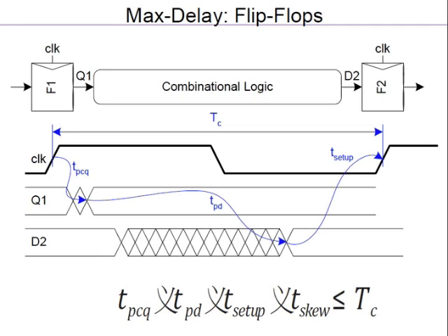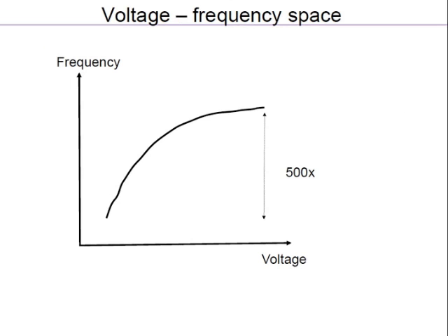You don't want the data to change before that. So that is hold time. That doesn't come in the critical path, but it is important for making sure everything runs properly. It doesn't determine the speed at which the chip runs. We'll discuss that more when we talk about timing and clocking later.